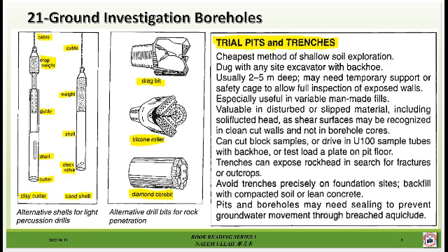Avoid trenches precisely on foundation sites. Backfill with compacted soil or lean concrete. Pits and boreholes may need sealing to prevent groundwater movement through a breached aquiclude.